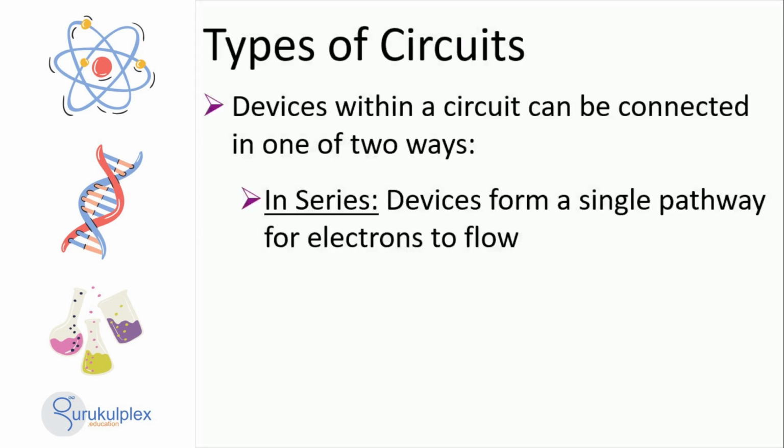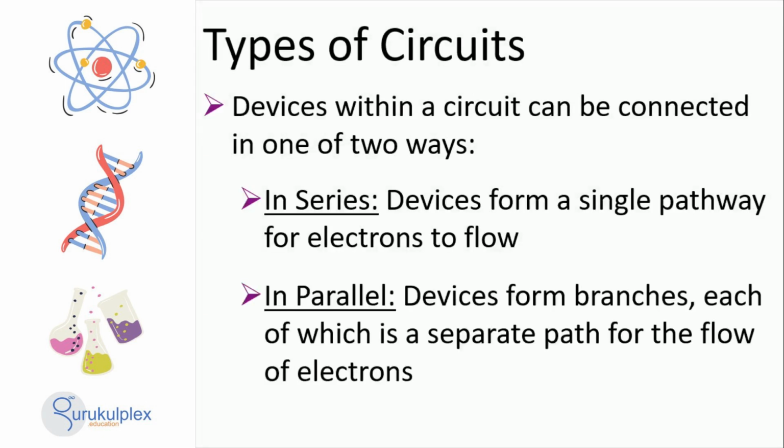When connected in parallel, each device has its own pathway for the current to flow through. This type of connection is used in applications where it is necessary to maintain near constant current flow to multiple different devices in the circuit. As each device has its own resistance, the total resistance of the parallel circuit is equal to the reciprocal of the sum of the individual resistances within the circuit.